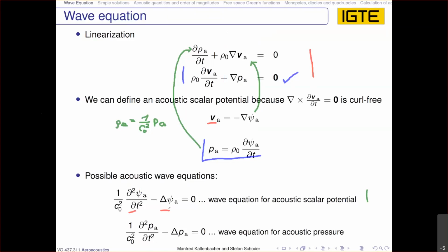Okay, so you see this is our fundamental equation for describing the propagation of acoustic waves in non-viscous fluids. Non-viscous fluids means we just neglect any viscous effects. And we should be precise: it describes linear wave propagation, so waves with small amplitudes concerning the acoustic density, acoustic pressure, and acoustic particle velocity.